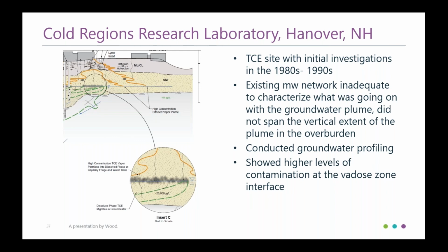So what they did end up showing was entirely different. Because of the profiling that they did, they figured that the conceptual site model is actually that they have a large soil vapor plume which is dissolving into the groundwater at that interface, and that DNAPL never really made it down that far. So you can see in the conceptual site model, the release is at the surface, and as it comes down, it's really just getting absorbed to the materials and doesn't make it all the way down to the aquifer as a DNAPL.